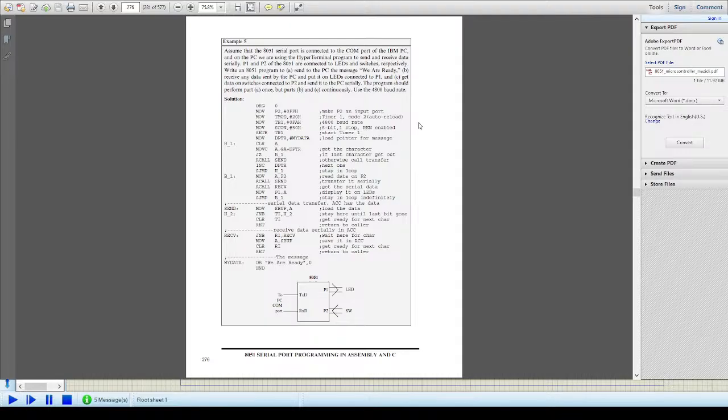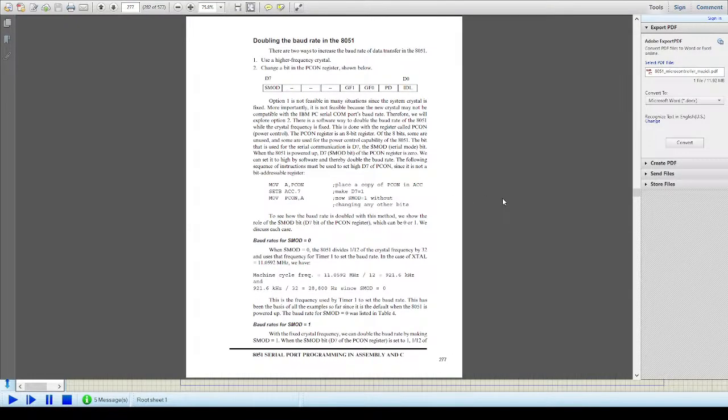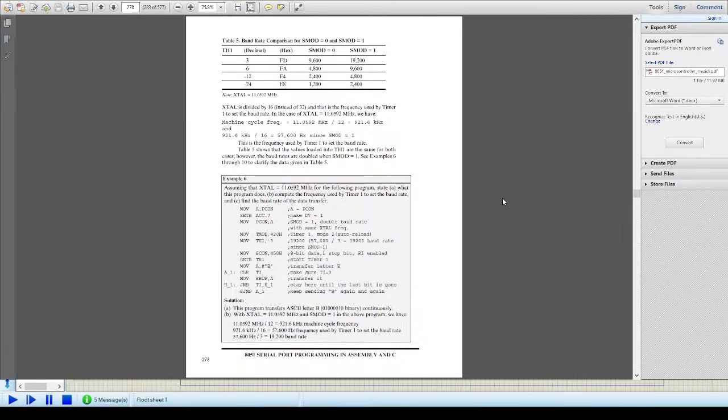Oh, okay. So you can go to this example, and it makes use of the data pointer. In this program, you can essentially write a string in a certain part of memory, and the whole string will be read through the data pointer, and it will be loaded to the SBUF register sequentially. As I told you earlier, it's the same thing. You can see all of the registers in detail, and play with the registers, to get a detailed overview of how things operate.